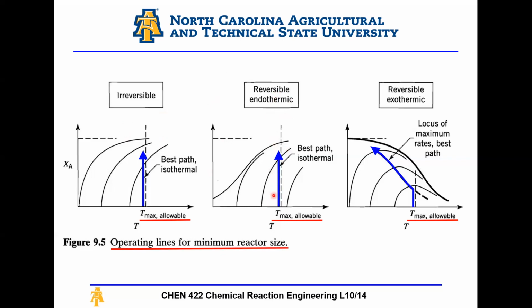And this highest possible temperature doesn't mean how high you can turn up your furnace. It means how high your reactor materials can support, what thermodynamic data for your species is available, and what production metric you're targeting. So if I want my products to be at 95 Celsius, then maybe I want to operate at this highest possible temperature. If I can only remove heat at a certain rate, I want to operate at this highest possible